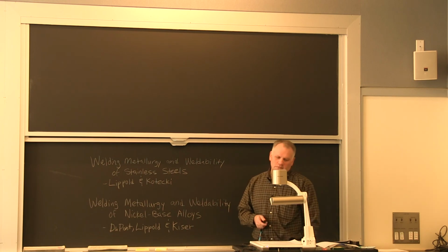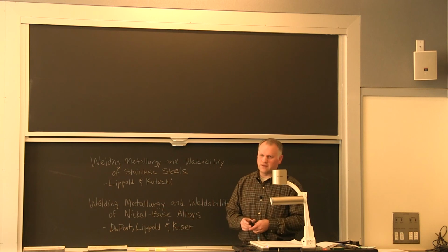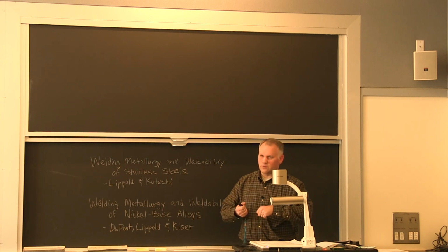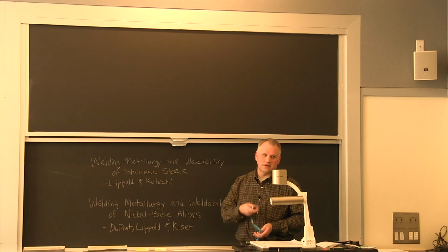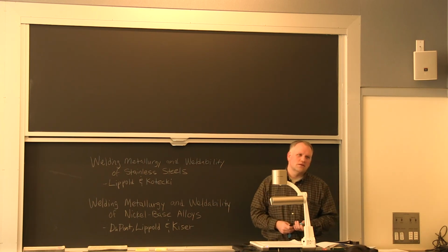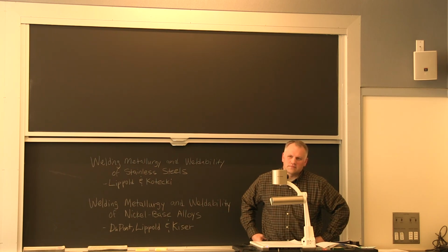Well, metallurgically, they're different terms. As far as effects, they're similar, but toughness has to do with the amount of energy that something can absorb. Ductility basically has to do with when it's coming apart, the type of fracture that you get. I guess it does have to do with the amount of energy as well that it takes to come apart. But ductility is measured usually in elongation, stretch. Ductility is a measure at slow strain rates. Toughness is often referred to at higher strain rates, impact energies, hitting it with a hammer.